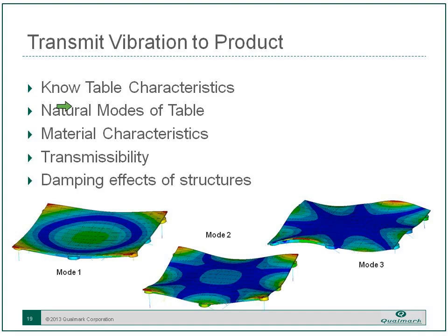Key thing, of course, is getting good vibration transmission to the product. That's the primary point of getting the fixture designed right. And to do that, you need to understand the table itself. Realize that our table is not rigid.